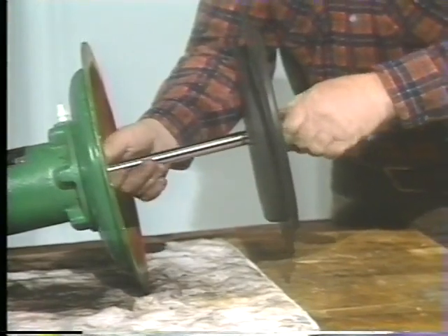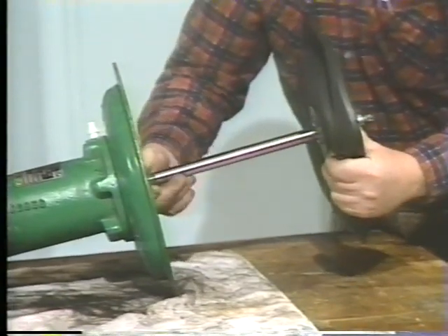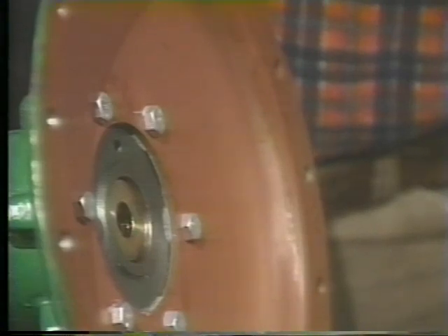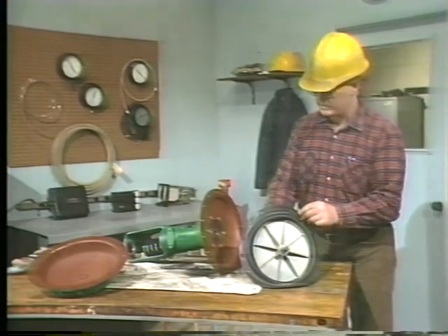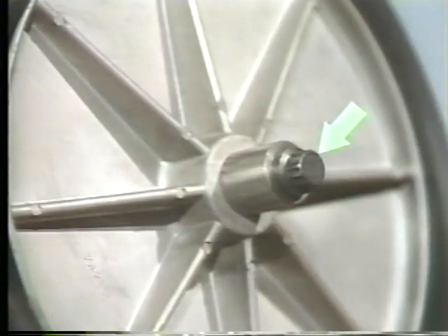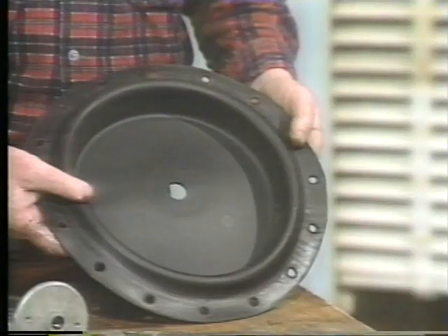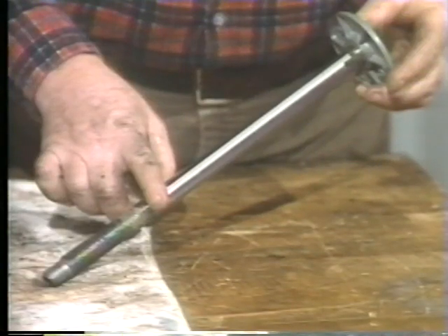Notice that the technician is extra careful when pulling the threaded portion of the actuator stem through the casing. He does this to avoid damaging the O-rings, which are used to form an airtight seal around the actuator stem. We'll look at the O-rings a little later, after the technician has disassembled more of this actuator. The technician can now separate the individual parts of the diaphragm and stem assembly. These include a bolt called the cap screw, a spacer, an upper diaphragm plate, the diaphragm, the lower diaphragm plate, and the actuator stem.